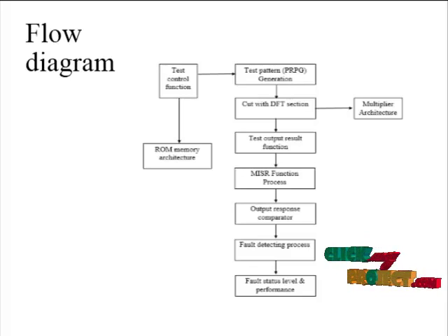The CPGC BIST engine becomes a part of the memory subsystem and the memory controller. The CPGC architecture consists of test pattern generators, defect detectors, a repository of failing addresses, an optional self-repair logic circuit, and configuration register. The CPGC can be programmed through the CR to automatically or manually repair memory defects detected with software.